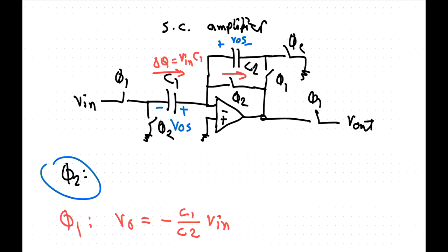They have less transconductance, but they have high output impedance, so you can get higher gain in them. So the main difference comes in the bits that become digital, like that digital amplifier we looked at the other day. Digital amplifiers aren't used very much, I think, but that was a cute idea.